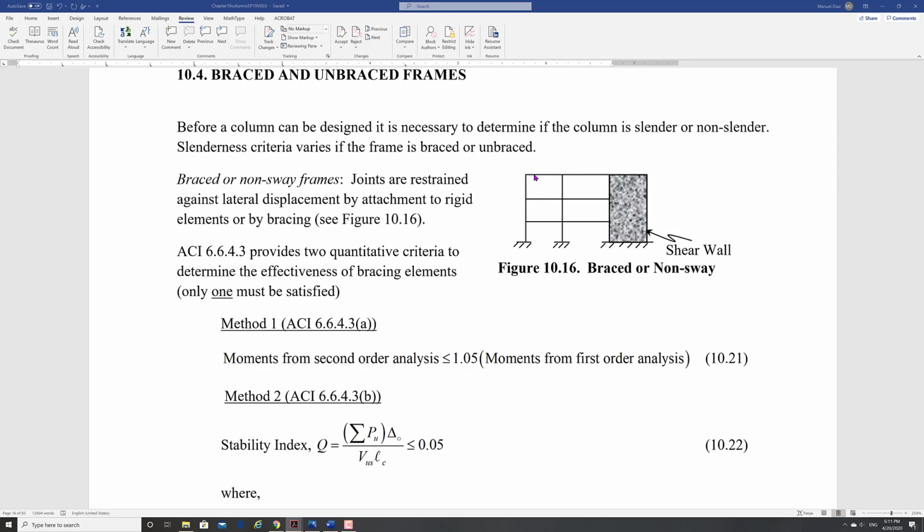You can include all that. You want to include creep effect, right? So all those things can be included. So there are different levels of second order analysis depending on the complexity of the problem, right? The more complex ones have all this geometry, non-linearity, creep, and shrinkage effects, and all that usually are at the level of research, more at the university level. The commercial ones do not have as much. Some do have a little bit. But they offer second order analysis, and they definitely give you the displacement effect. Okay, but that's another level of analysis.